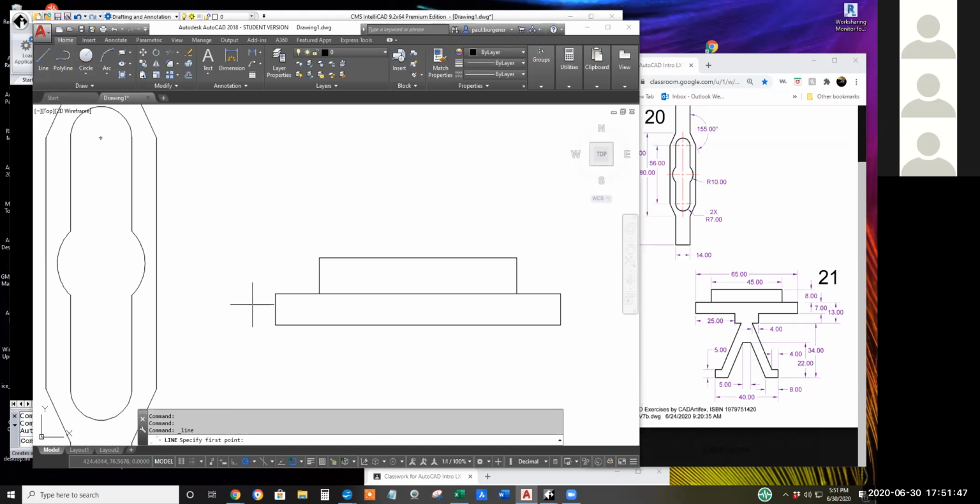All right. Start here, go in 25 and come down. A little arithmetic, this would be 6, enter. And I'll come a short distance and mirror these 2 lines about the center and trim away the garbage and erase the guidelines.